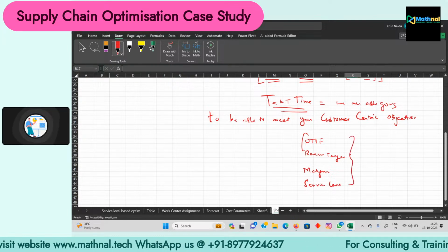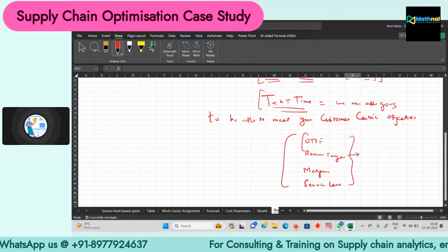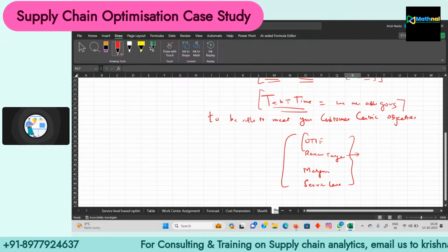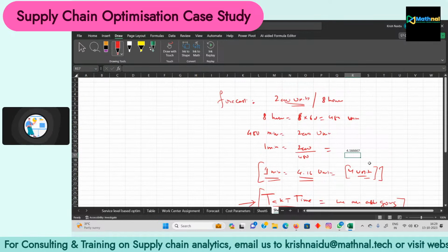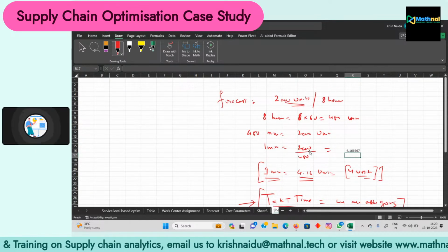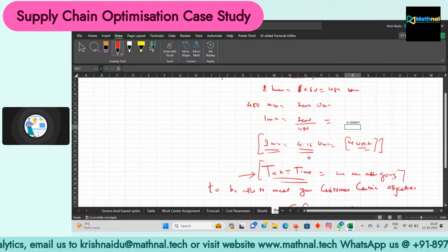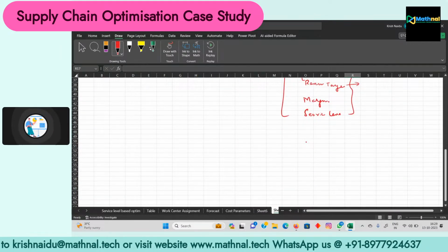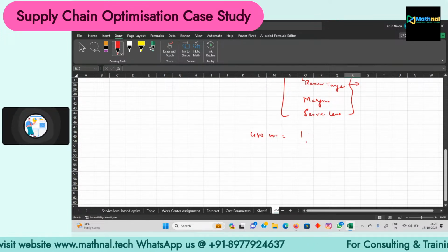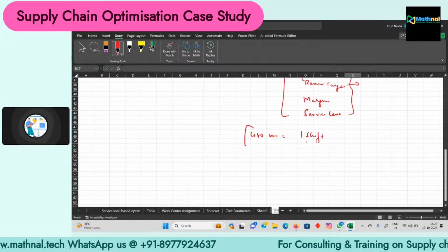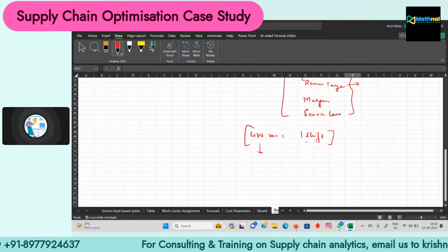So these are some of the metrics which you can achieve if we are able to meet our capacity as per the takt time. In 1 minute, suppose I have a total forecasted production of 2000 units, and I have to work in one shift. In one shift, I have 480 minutes. But it is not possible to consume all 480 minutes. Maybe suppose we have some setup time.